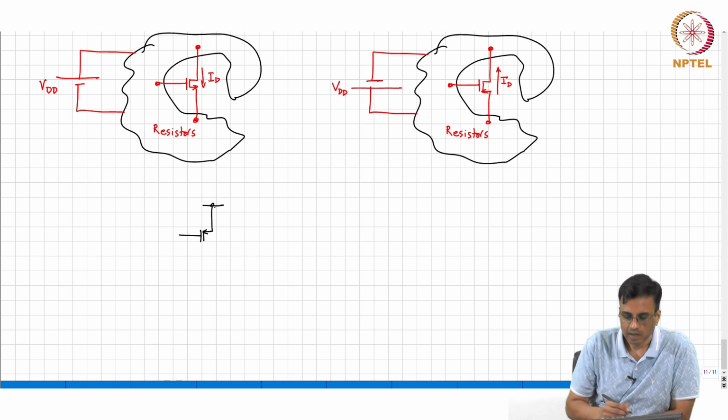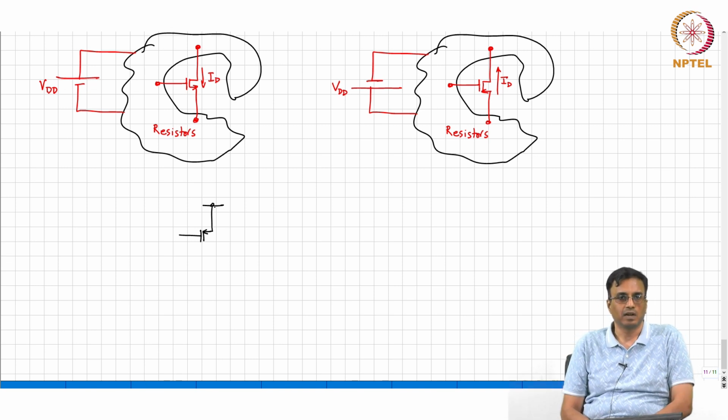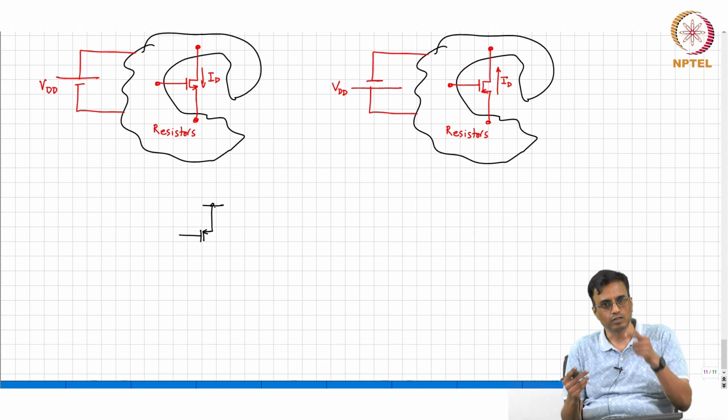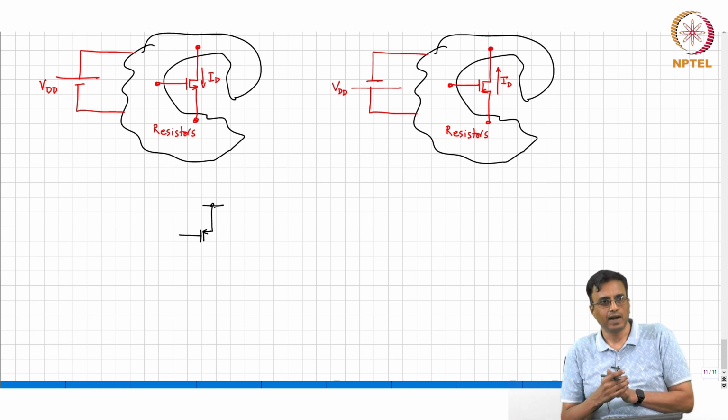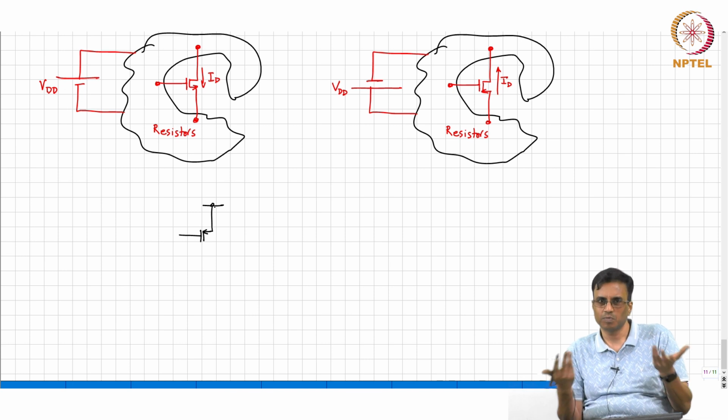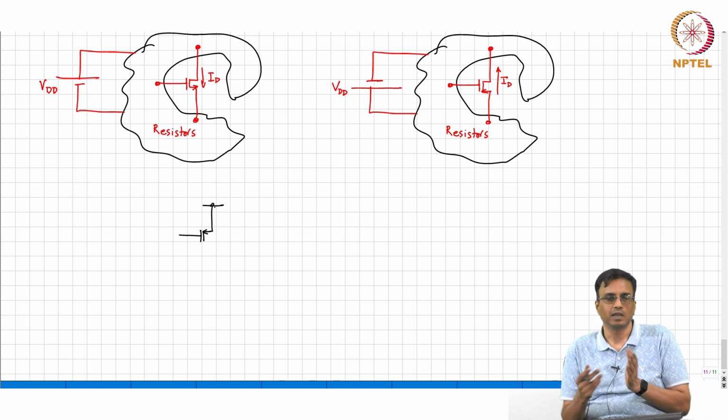remember, the PMOS drain current is controlled by the source gate voltage, and like in the NMOS transistor, the current can be measured in either the source or the drain. So not surprisingly, the same bias techniques that we used in the NMOS case will apply for the PMOS too, right.